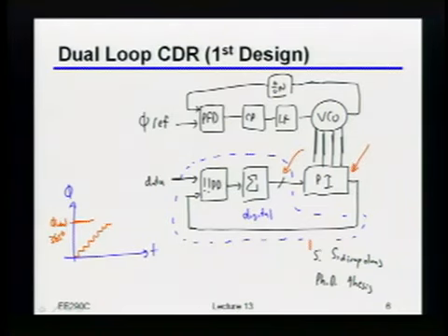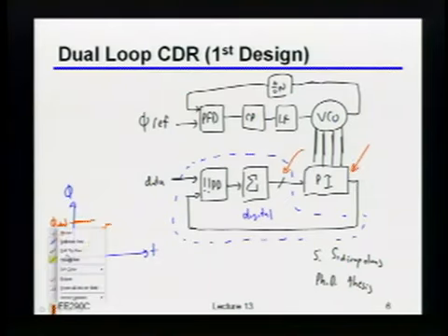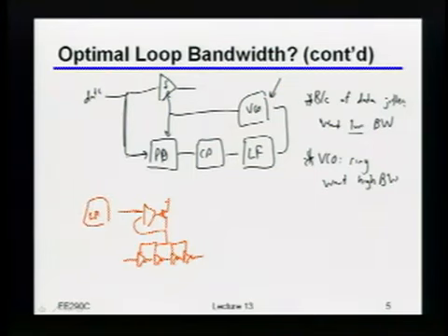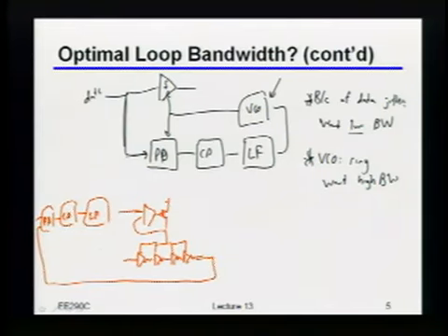Yeah. So why does the analog get stuck? Okay, so it depends on how you've built the analog loop, but imagine that I just build a loop that looks like this, and I'll draw it over here. So imagine that my delay line was just a pile of inverters, right? And then the way I build that loop is I just regulate the supply of those inverters. So I've got my charge pump plus loop filter here, right? And I've got my phase detector, and then that just feeds back from here, right?